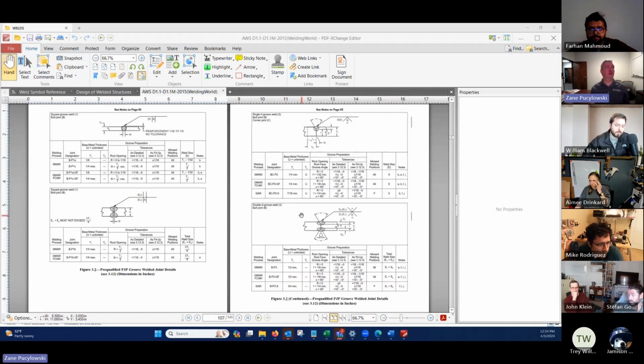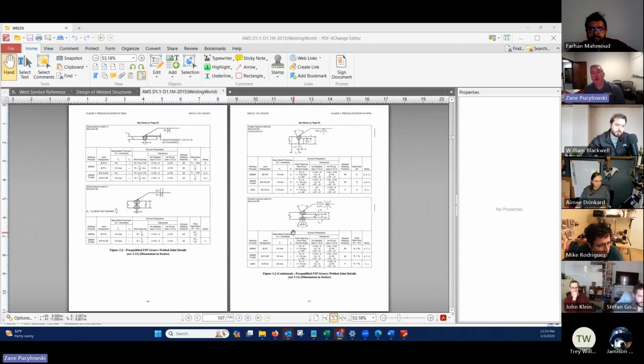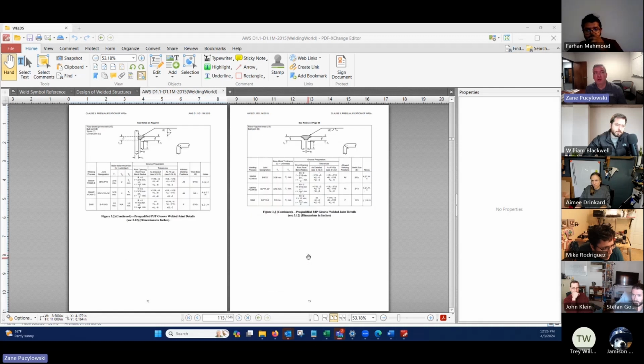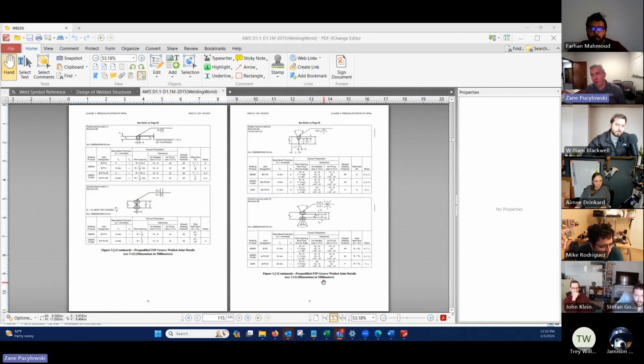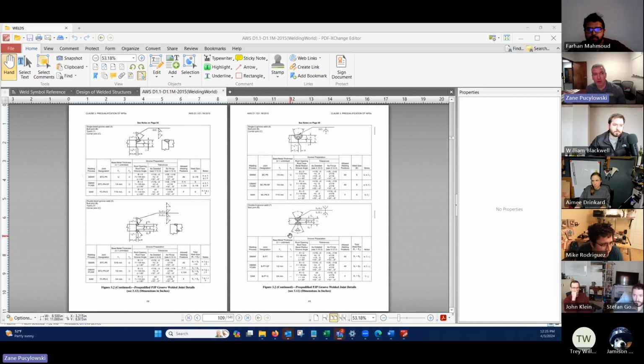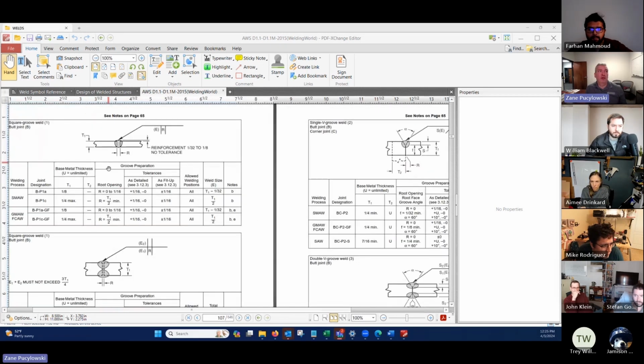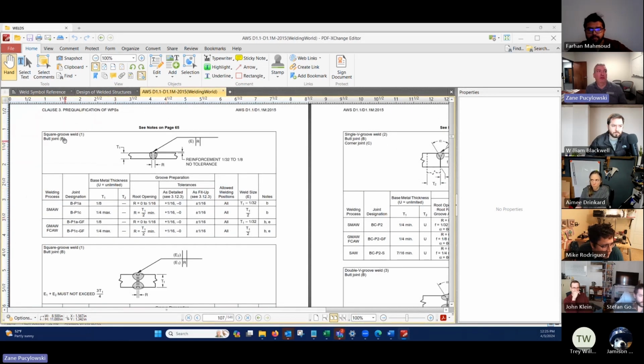Figure 3.2. Okay. So this I pull up a lot and look at with you guys, and it's extremely important. There's not a lot of different tables. There's one version in inches and exactly the same, but in millimeters. So there's not 37 different joints. There's some shown twice. Make sense? And what this tells you is how to make a good weld. So if I wanted a square groove weld MIG process, I can weld 1/8 inch with these parameters and this note and make a good weld.